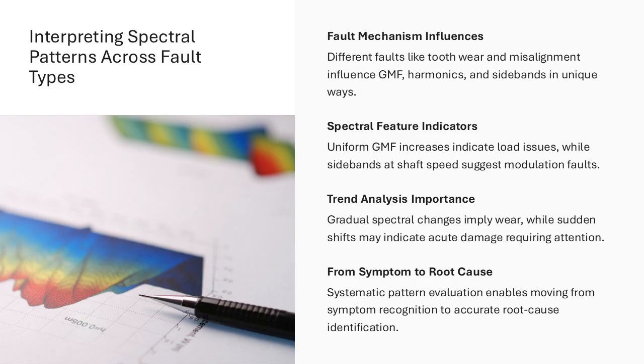Trend analysis is particularly important. Gradual, consistent changes typically indicate wear-related issues, while sudden spectral changes may signal acute damage. Comparing data across operating conditions further improves diagnostic confidence. By systematically evaluating these patterns and understanding their physical origins, engineers can move from symptom recognition to root cause identification, enabling more accurate maintenance decisions.